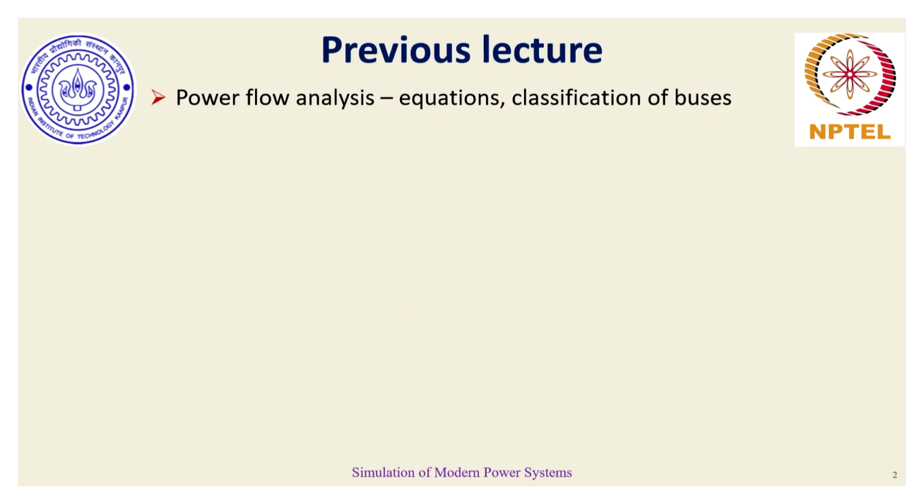In the last discussion we finished the different types of equations involved in power flow analysis, and in order to solve these equations, what types of buses we have to assume so that we can ensure mathematical consistency or numeric observability in terms of the equations involved and the corresponding unknowns, in terms of voltage magnitudes and phase angles, or the real and imaginary parts of voltages, based on whether we choose the polar version of voltage or the rectangular version.